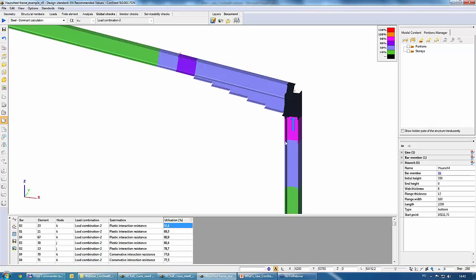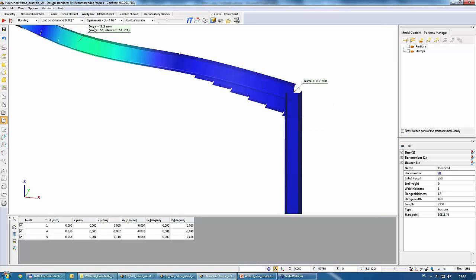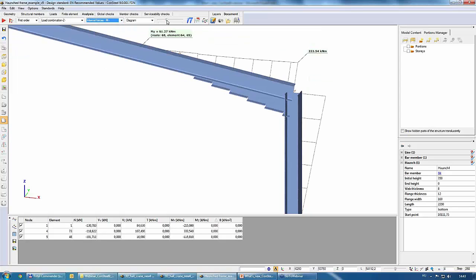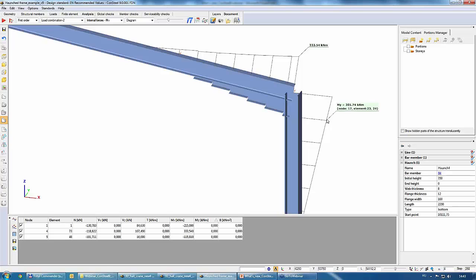And if it is done, since the bending moment diagram, as we see here, is dropping down significantly, we can see that instead of 354, we use this design value, which is 302, which is significantly lower, almost 20% lower, and that has a beneficial effect on the utilization of our column member.